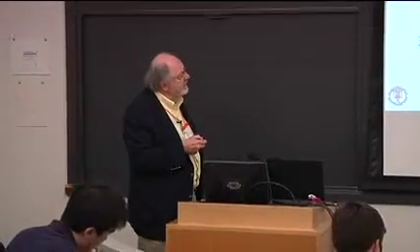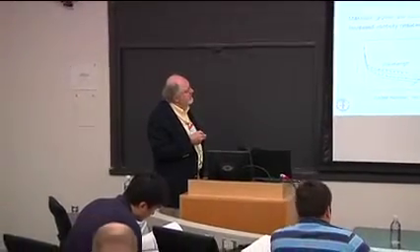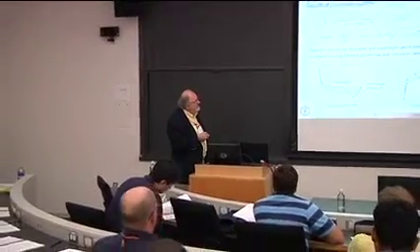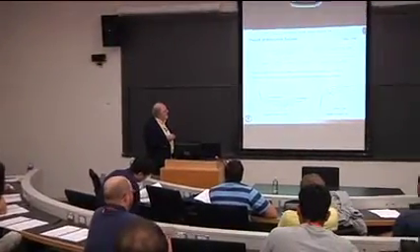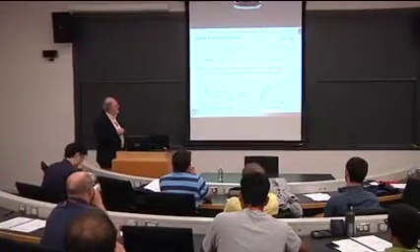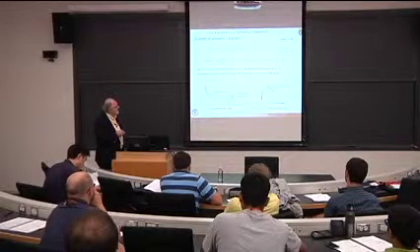So we've done some curve fits of those solutions and come up with these expressions in the wave breakup model. So here's the non-dimensional wavelength, and here's the non-dimensional wave growth rate. Function of essentially three parameters here. The Weber number that I just spoke about, the gas density, the injection velocity squared, the radius of the jet, and the surface tension. And then the Ohnesorge number, ratio of the Weber number and Reynolds number in the liquid phase. And then finally Taylor's number, which is Ohnesorge number times Weber number.